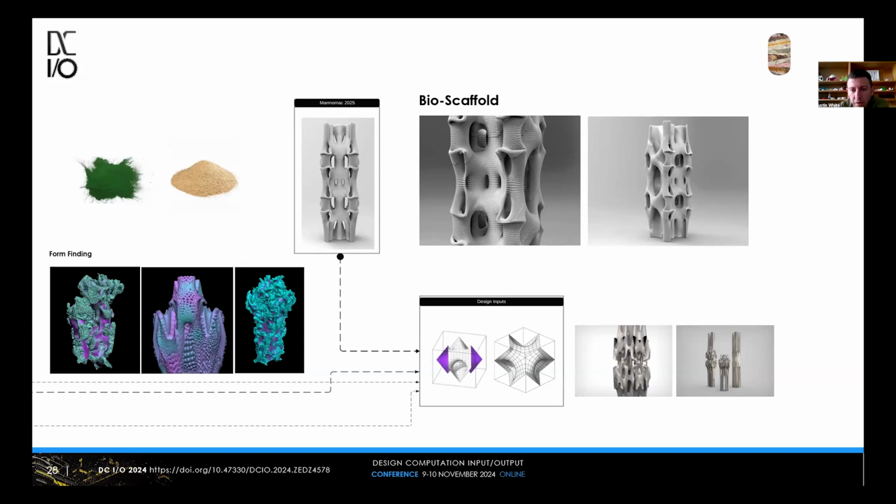It's a structural component designed to mimic natural porous scaffolding found in biological organisms in architecture and structural design. Bioscaffolding columns offer a sustainable biomimetic alternative for load-bearing structures. They can enhance indoor air quality, serve as green walls, or produce insulation while supporting the weight of architectural elements. Functionally gradient design is a method that we're trying to employ here, where 3D printing allows these columns to vary in density, porosity, and composition throughout their structure, enabling customization for specific applications. So in architecture, this could mean stronger, denser materials near the base and lighter, more porous materials towards the top.